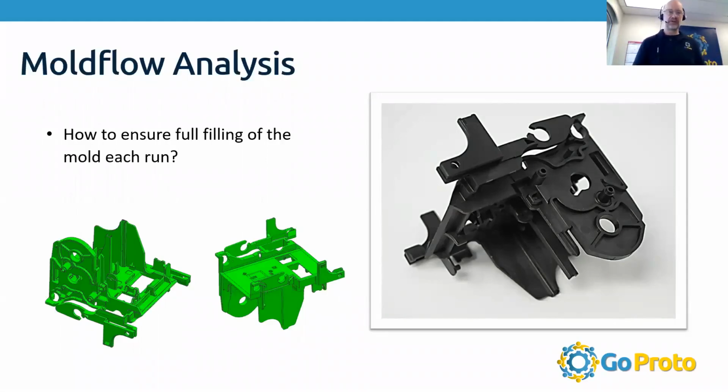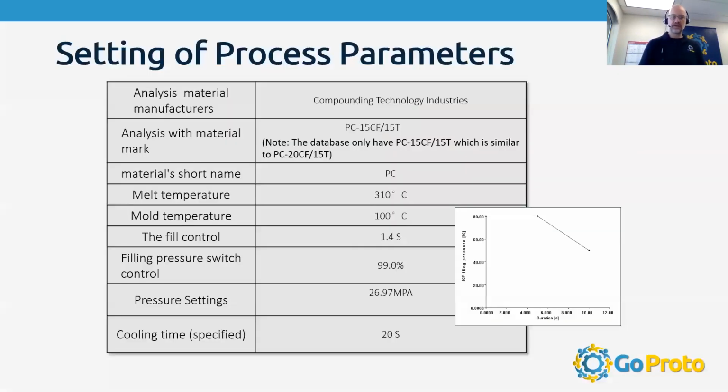We have enough experience that we can often put that knowledge into play along with that initial DFM and say this part is safe enough that you don't really need to run a Moldflow. It's going to be fine as is. Sometimes we're not quite sure, or the customer wants it for their future process, or to put in their project folders and show that this was completed. So in this case, we did run a Moldflow through the software, and you'll see as we go into the next slide, we start.